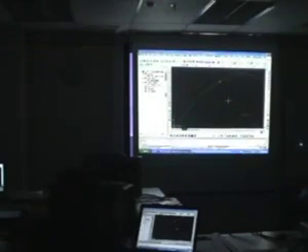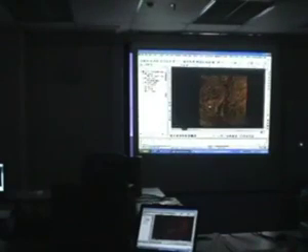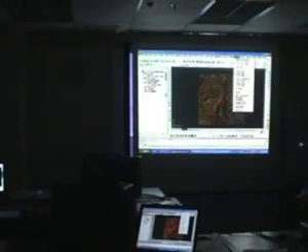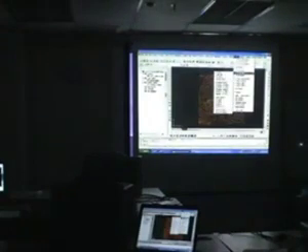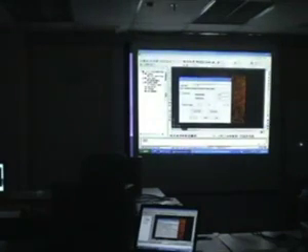So this is about contour lines for Autodesk Land Desktop. Just to give you a bit more about the display, aside from the triangles and the contour lines, there are also many different ways in which you can represent the surface. I'm going to show you one which is quite unique. This is surface elevation shading, meaning I'm going to color the surface based on the elevation ranges.